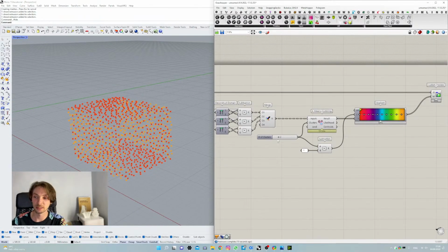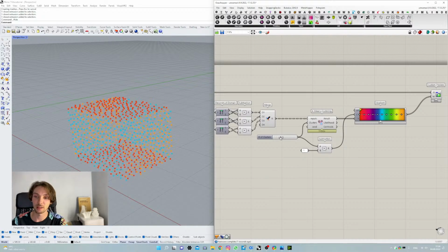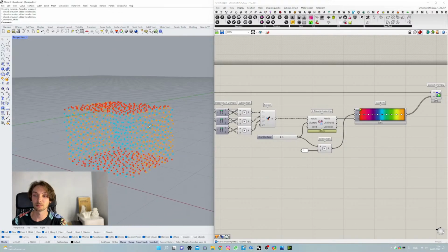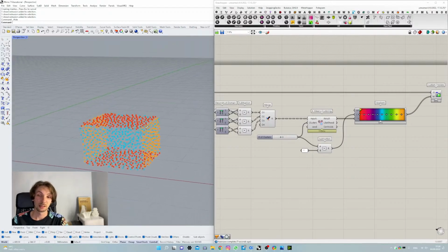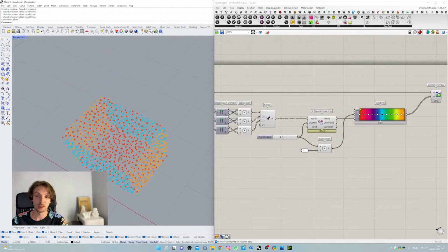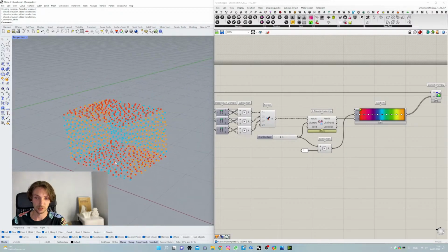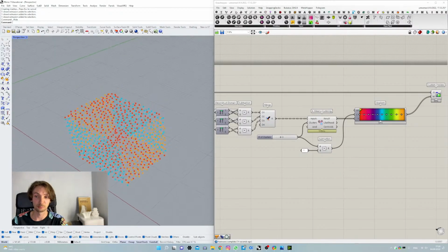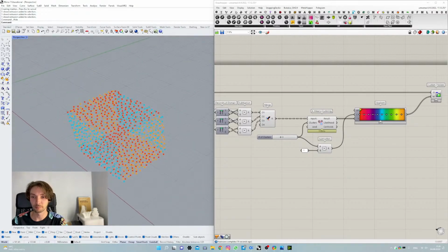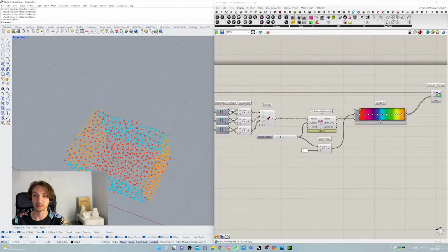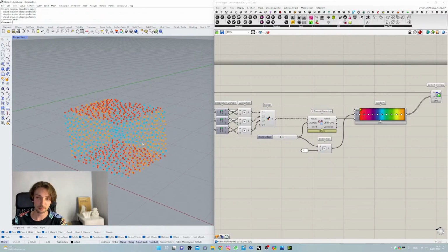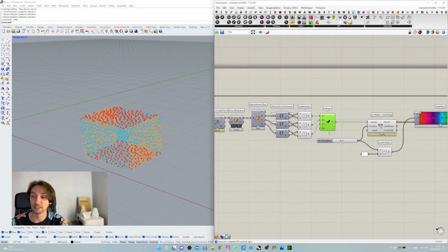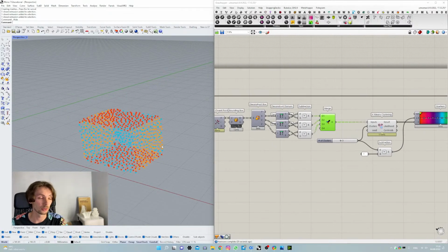Let's change the number of clusters and we'll see how it changes. What we have right now, we have parallel walls colored with one single color, right? Red for ceiling and floor. For walls in X direction, we have blue, and orange for the Y direction walls. That happens because our input is the same for these walls, right?